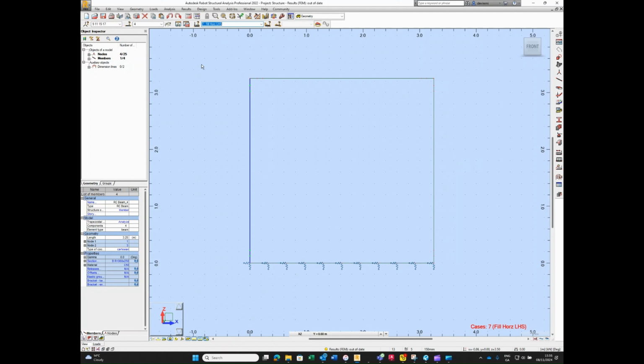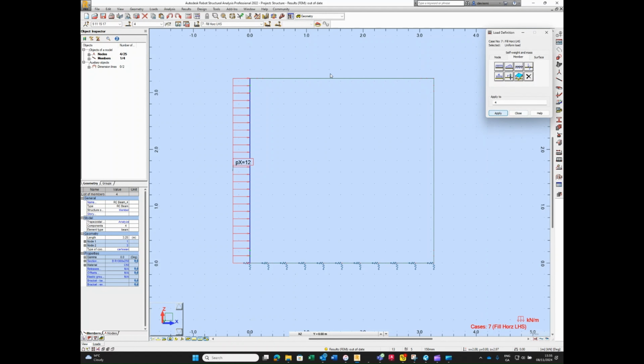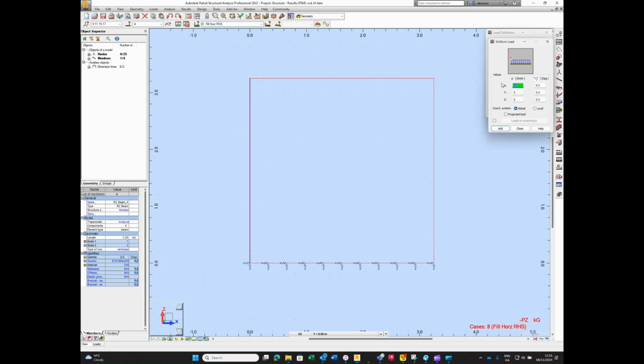We also have our fill on the left hand side, so this will be a triangular load, and it'll be the depth of the culvert. Again, I think the culvert is 3.25, so it's going to be 3.25 by our 20, which means we have 65 kilograms at the bottom, up to 0 on the top. The horizontal surcharge on the side walls, due to the depth of fill, the 600 mil hasn't been applied, but it should be applied. That's the 12 there, okay?